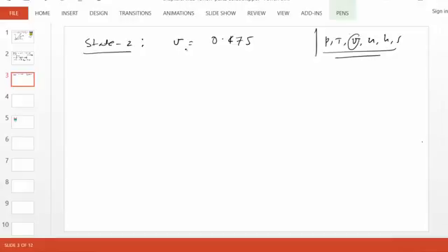So to find another property, we realize nothing else is given to us except the heat transfer. So if we apply the energy equation for the heating process, the energy equation, if you recall, delta E equal Q minus W external. If we neglect KE and PE, then it becomes delta U equals Q. And there is no work in that case. There is no shaft, there is no electricity, there is no boundary work because the system volume doesn't change.